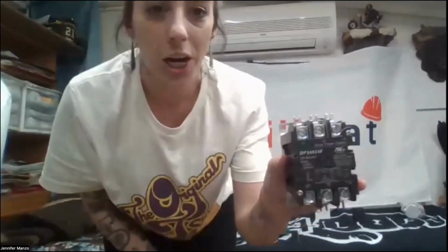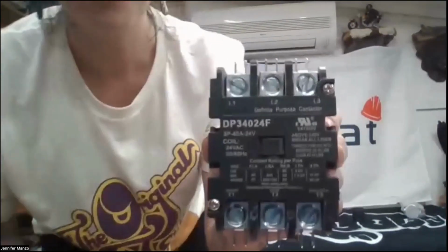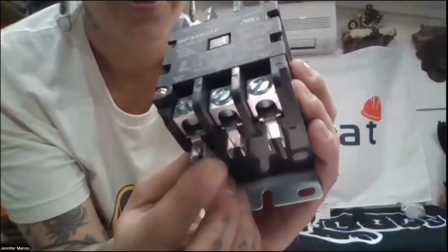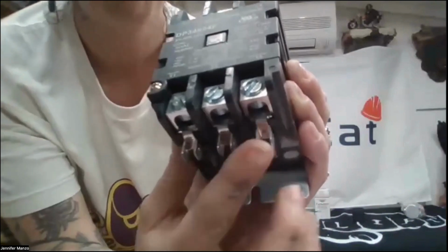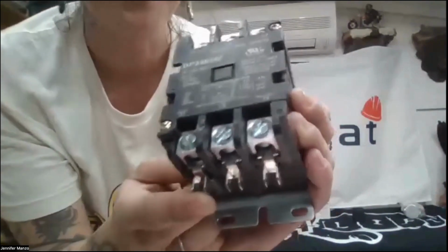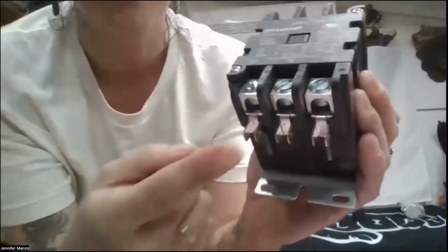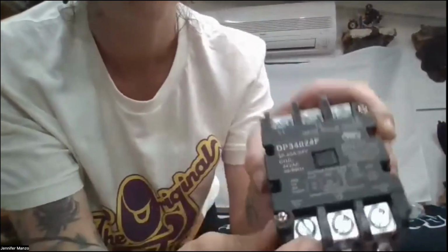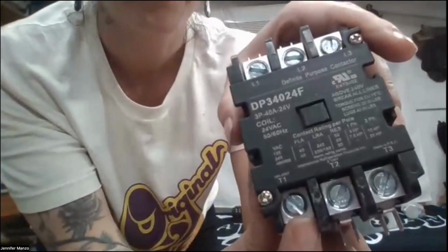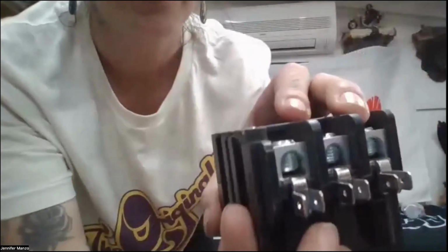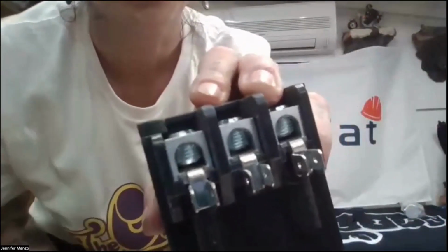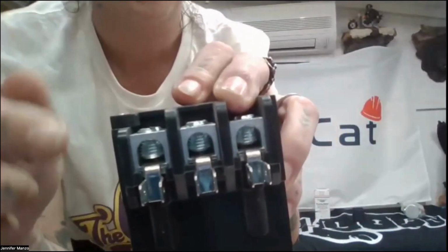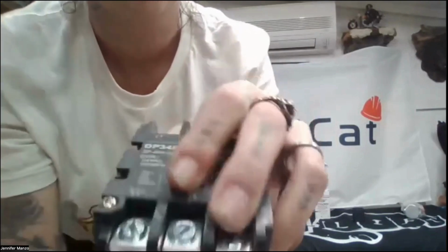Okay, so this is a contactor. As you can see, like I showed you guys before, you have your contactor pins. This is where your wires go. Well, sometimes. If your wires have a bite head on them, we call them bite heads, then that's where they go. If they are just a loose wire and you're not putting a head on it, they go behind these nuts. This pulls out. As you can see behind there, there's a little gap behind the nut and the backing plate. So that will pull out. You stick your wire up in there and then you tighten it back up.